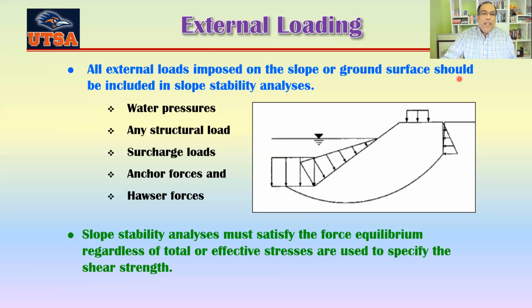So these are the loads you must consider, like water pressure, any structural load. Like if you have any roadway here, then you have to show that one here. And then surcharge load. This is your surcharge load. Let's say your traffic load, then anchor force and hawser force.